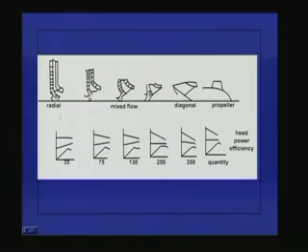The reason is one can achieve the maximum efficiency by designing a radial flow machine as compared to the efficiency that can be achieved by going in for an axial flow machine. So, as the specific speed increases from 35 to 75, then to 130, we go for a mixed flow impeller, where the entry is radial but the outflow is in the axial direction, or we can go for a diagonal when the specific speed is 350, and at very high specific speeds we go for a propeller pump.